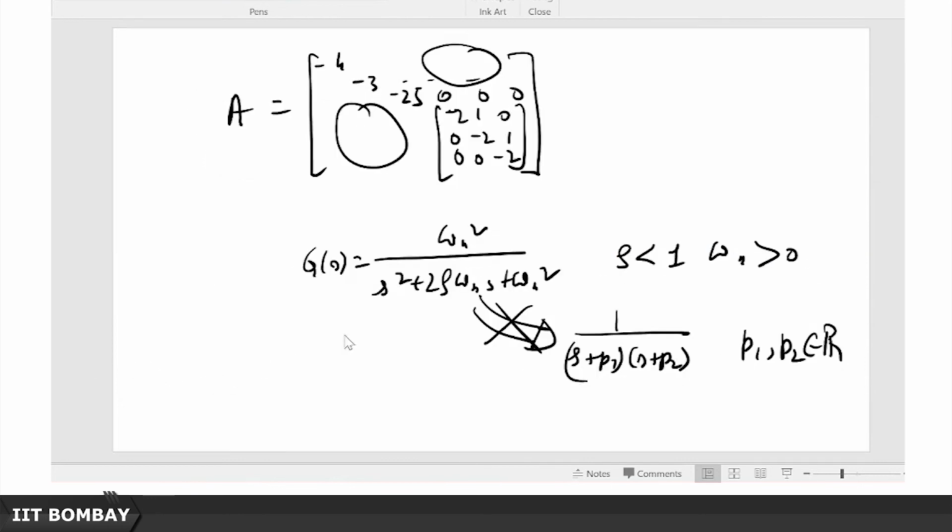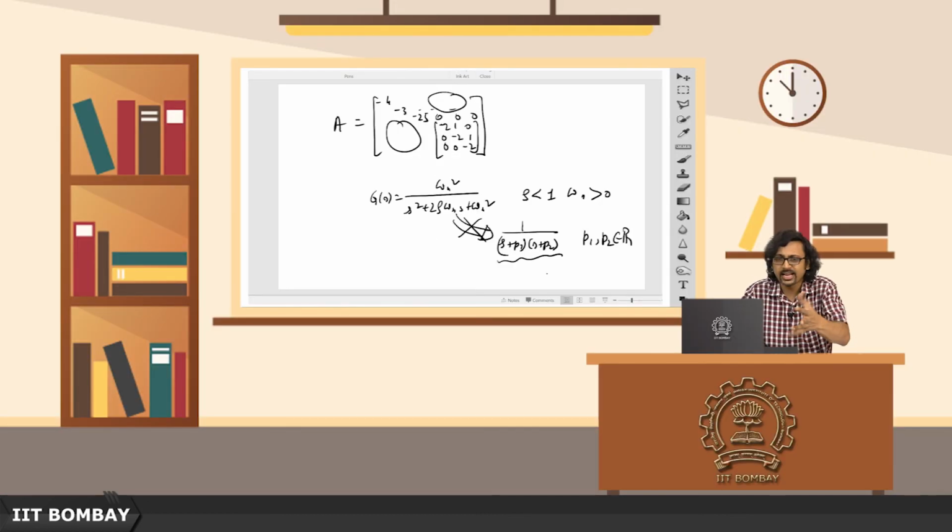But now the other problem is, even if your poles are not repeated but if they are complex, you have to after all realize this using some real parameters. You cannot realize complex numbers using real parameters like your resistances, inductors, capacitors, those are real variables. So you cannot split it up into this sort of a factorization and then realize it.